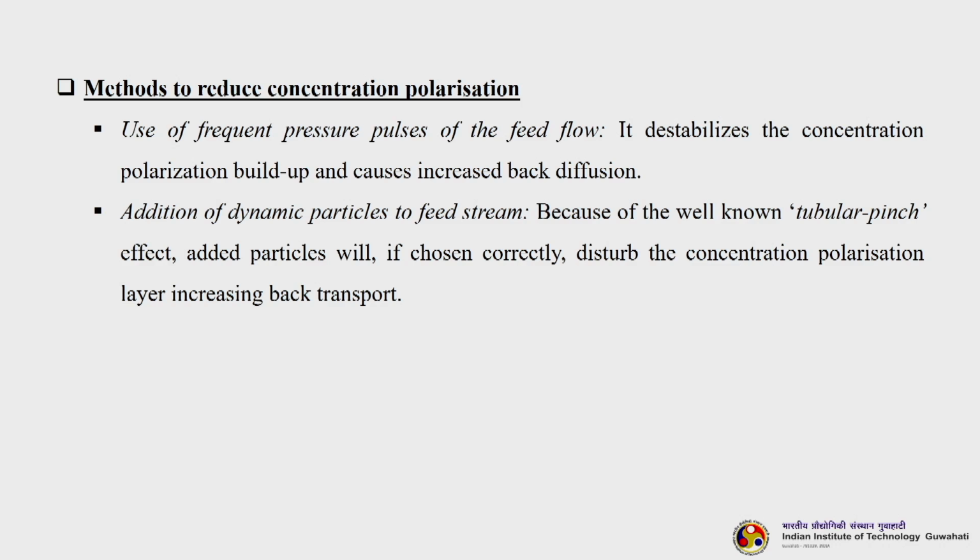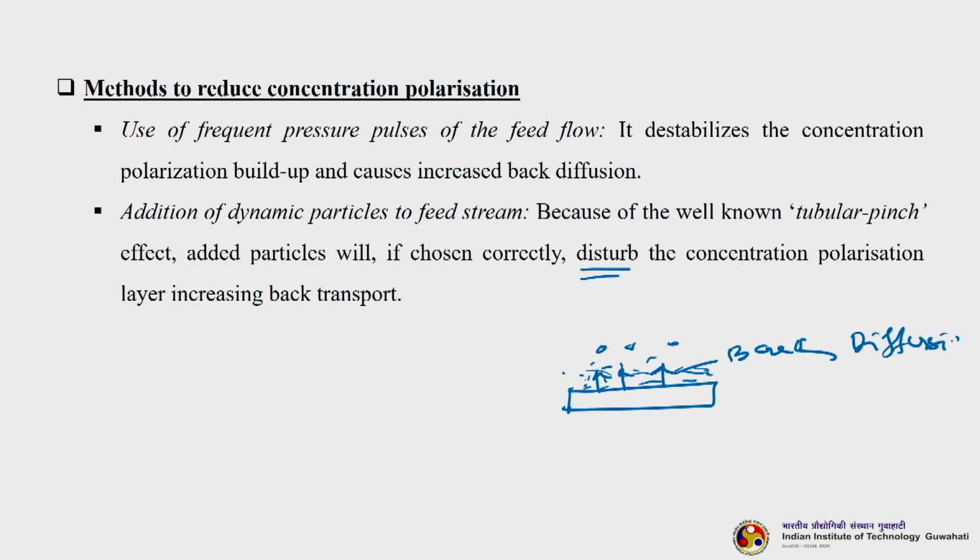Then, addition of dynamic particles to the feed stream. Because of the well known tubular pinch effect, added particles will, if chosen correctly, disturb the concentration polarization layer by increasing the back diffusion. So, suppose this is the membrane, and concentration polarization is happening here. You add some particles. So, what will happen? They will try to come here and increase the back diffusion. When it increases the back diffusion, the chances of these solutes getting deposited on the surface of the membrane reduce, thereby reducing the concentration polarization and of course, subsequent fouling also.